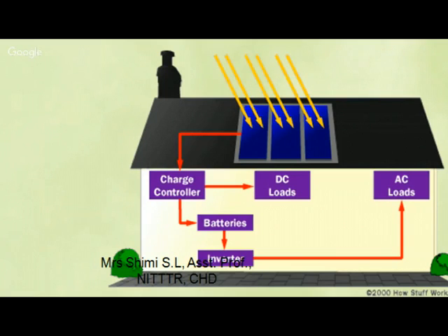Yeah, you can do it like this. You have a solar panel, sunlight falls on it, you get an output voltage there, and this voltage is not constant, is it? It varies with the irradiation. So what should be done? You cannot go and connect it to the load directly. So you have to store it in a battery. Okay, so for storing in a battery, what is the battery rating? Like what is the voltage rating of the battery? 12 volts or 24 volts, not more than that, is it?